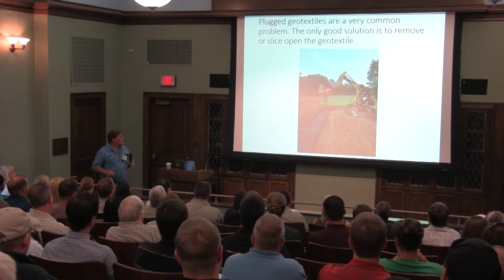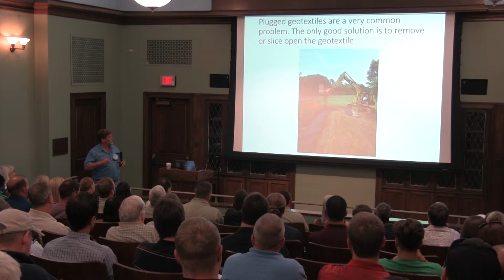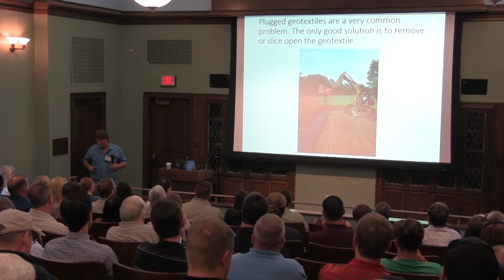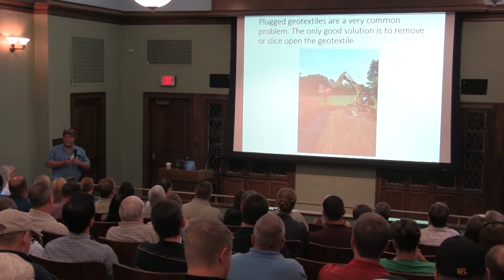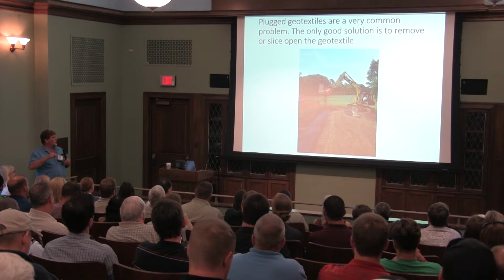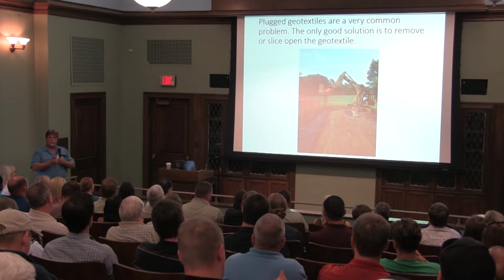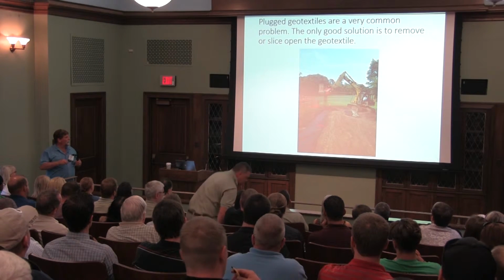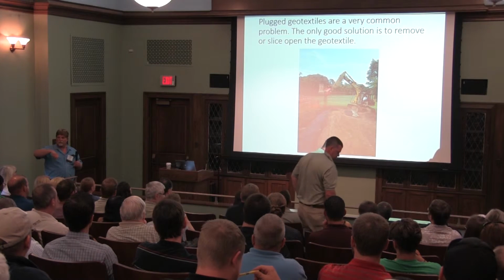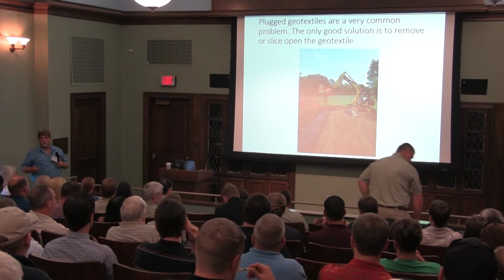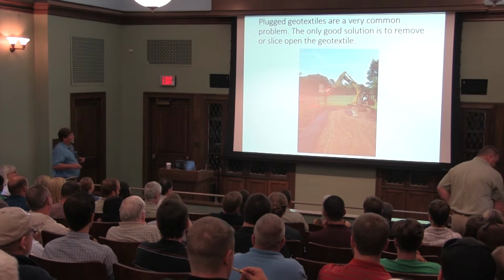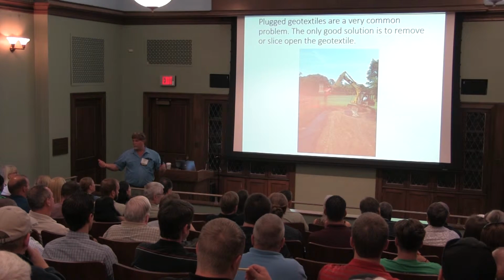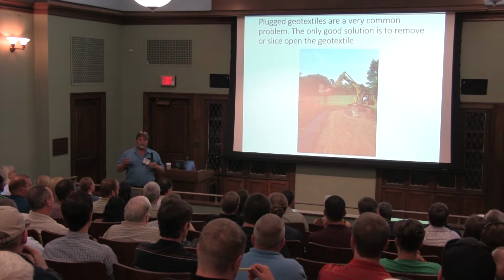Okay? We're going to talk, again, we'll go back to this whole Geo Textile thing. This was actually not an infiltration trench. We were actually exfiltrating out of this. This trench was taking water off the street into a gravel trench, and then the water was going out of the trench into the soils. There was a little bit of a retentive grading dish on top that takes some runoff water, but we weren't getting a lot of runoff here. So in this particular situation, the water was going into the pipe and pushing out through the Geo Textile. Theoretically, it's going to keep it clean.